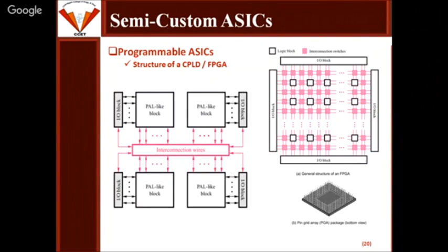In this case, you can see that the interconnection wires are basically red in color. The devices are basically centered around these interconnections. So we can use fuse or anti-fuse technology, the fusing of the interconnection, and then the interconnection will be formed. You can think of it as different relays between the devices.